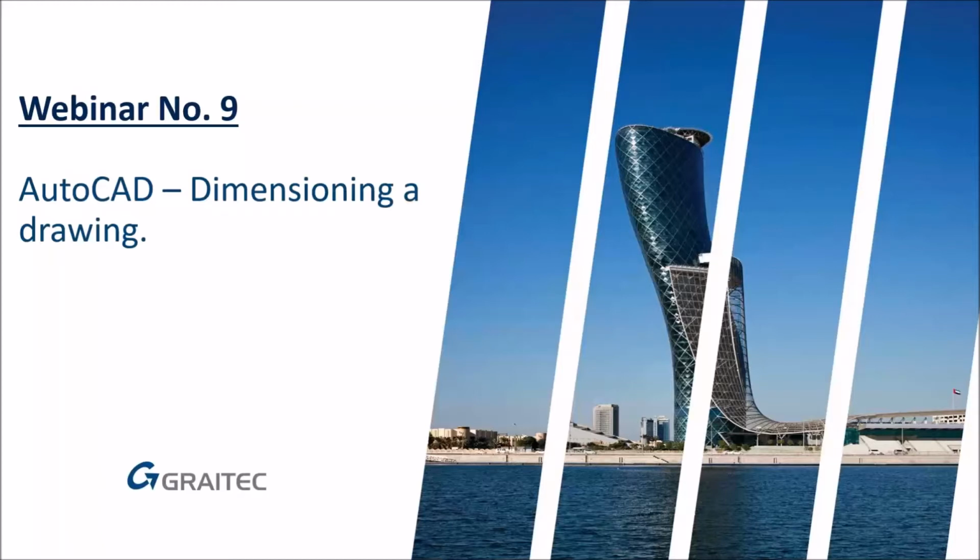So yeah, set up dimension styles, dimension model space, paper space, annotatively. We'll look at if you're doing some engineering drawings, you might want to put tolerance dimensions on there, with your plus and minus a few thou, or fraction of a millimeter or whatever. Dimensioning enhancement tool. How do you tidy dimensions up on a drawing?